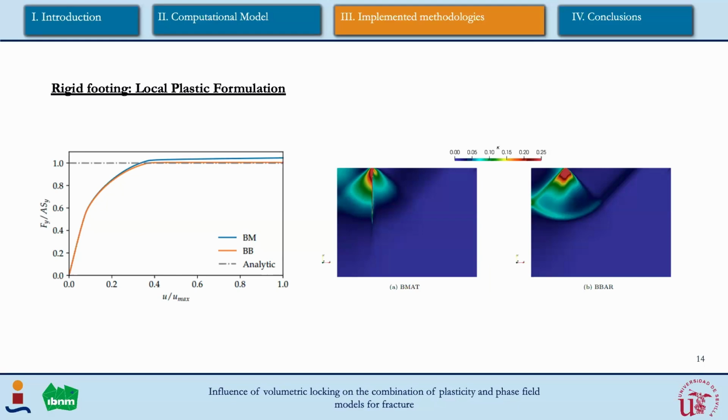As for the morphology of the yield surfaces, we can also see differences. In the normal B operator model, we can see the formation of a vertical shear band, whereas in the B-bar method, we can see that it correctly predicts the yield surface that the Brinch-Hansen method says.